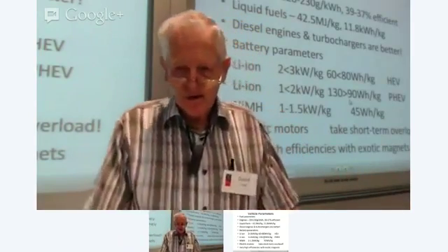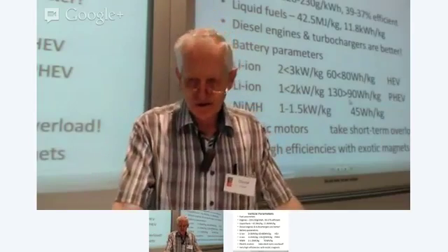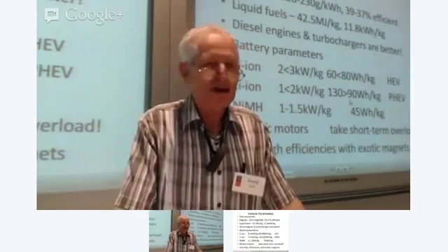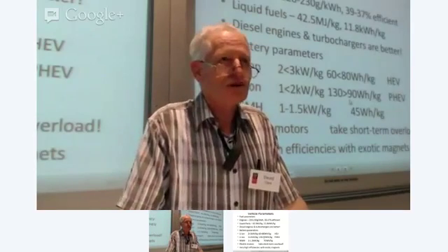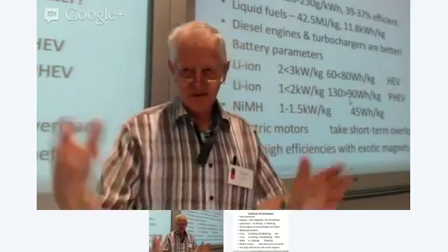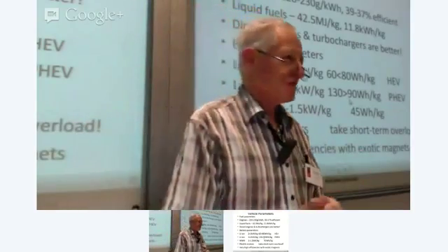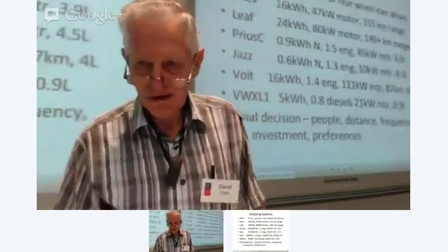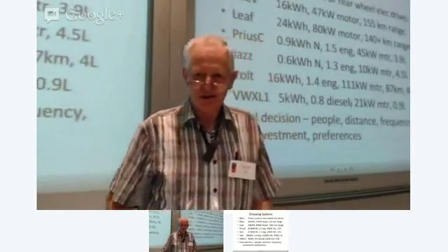As far as electric motors are concerned, yes, you can get very high efficiencies, but I just need to put the proviso there that it's with exotic magnets, which cost you a lot of money. So while you can get 98% efficiency type motors, you'll have to pay for the privilege of doing that. Well, let's now look at choosing systems.